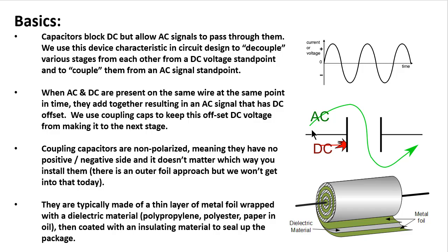Another interesting little thing here: coupling caps are typically non-polarized, meaning they have no positive and negative terminals, and it really doesn't matter which way you install them. I'll throw out a caveat here. There is an outer foil approach that would say that maybe one side of the capacitor would be better to hook up than the other to the positive or negative, but that's a minute thing, and we're not going to talk about that today. For all intents and purposes today, coupling caps are non-polarized.